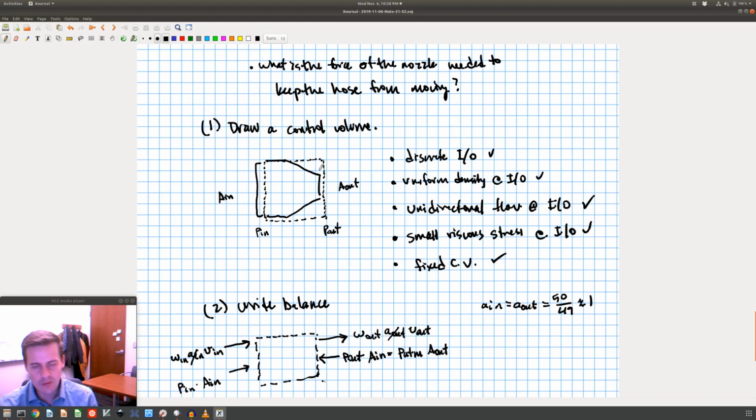So I also have atmospheric pressure pushing on this part and pushing on this part, and it's also pushing on that part. So I have atmospheric pressure all along those guys. Okay, so I have P atmosphere times A in, because the area along that whole part is A in as well. A out is only that little piece right there. So P atmosphere, A in.